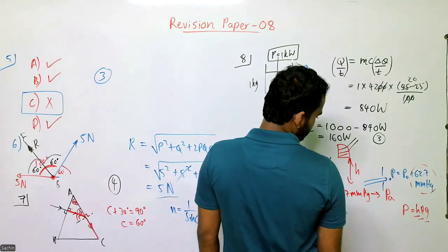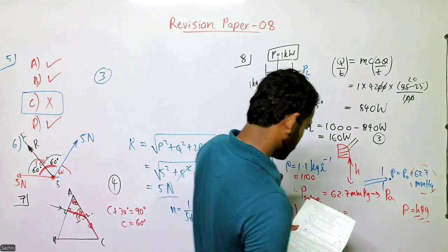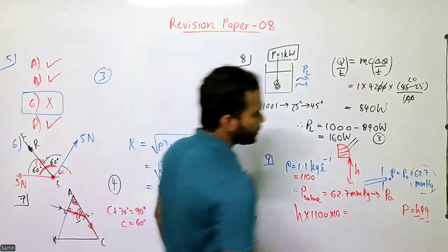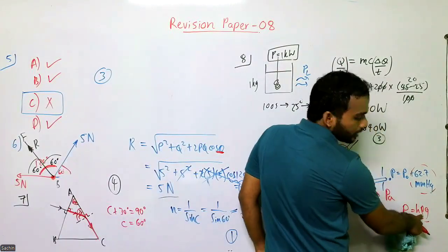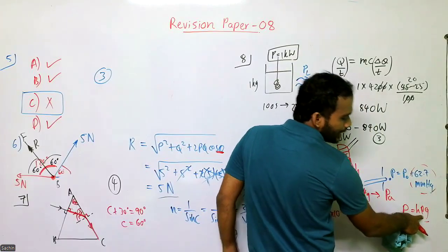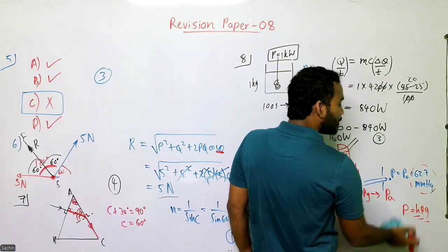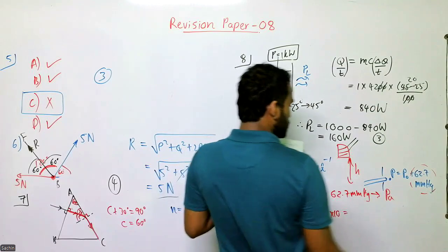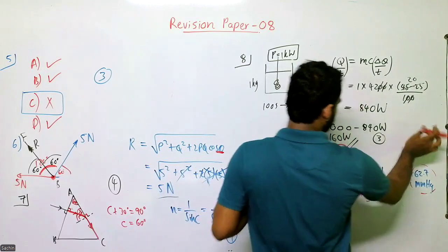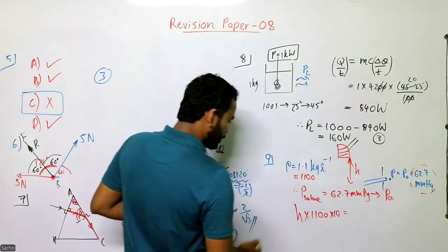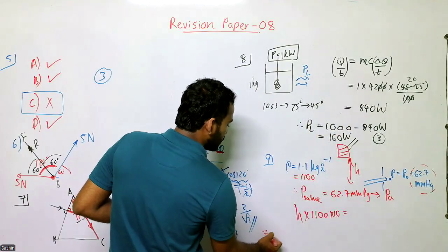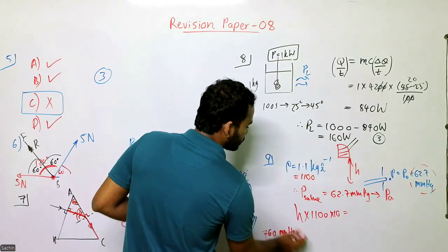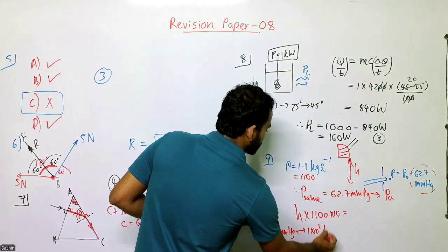In this case you can't use P equals h rho g, because they haven't given you the density of mercury. You can use this equation only if they have mentioned the density of mercury. That is not mentioned. But they have given some other information, using which you can convert this into Pascal. They have mentioned that 760 millimeter Hg is equal to 10 to the power 5 Pascal.